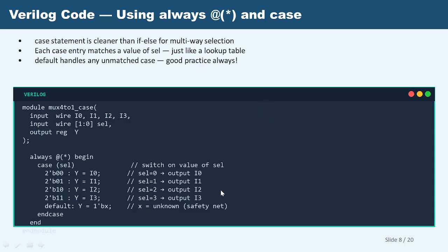So for thinking that, you are writing something called assignment statements. If our select lines are 0 0, the input I0, y is equal to I0. To store this value inside that y, inside that output, we need to store I0, right? For select line 0 0, to store that y value, you are giving y as reg.